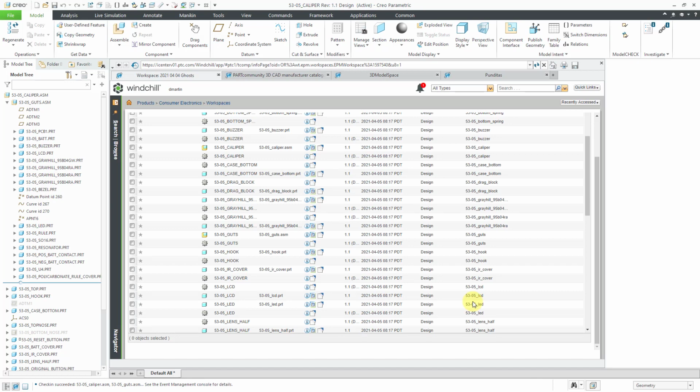So again, you can try to edit definition of the features. If that doesn't work and you just need to break the external references, you can try using the collapse command and also any other techniques that you have in order to use local native references as opposed to having external references to a file that doesn't exist. Once again, if you can use data sharing features for designing with external references, that is much preferable and can help avoid all these different problems.